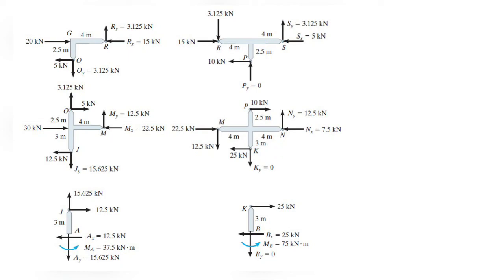So we take note for our shear, the exterior columns will receive a value of V, while interior columns will receive twice the value of your shear, or that is 2V. So what you shall do here, you will isolate first the upper segments.